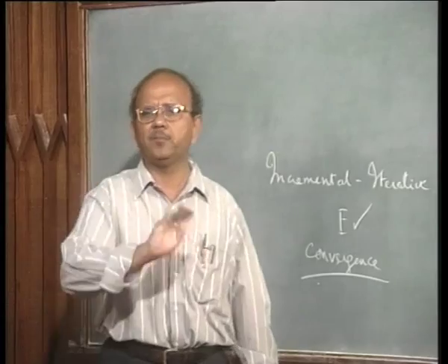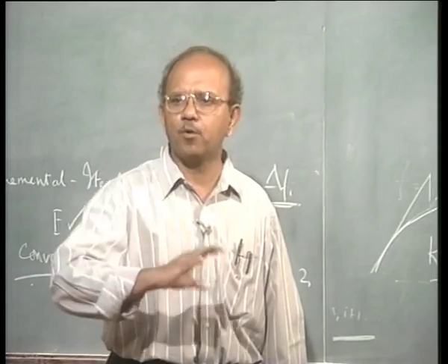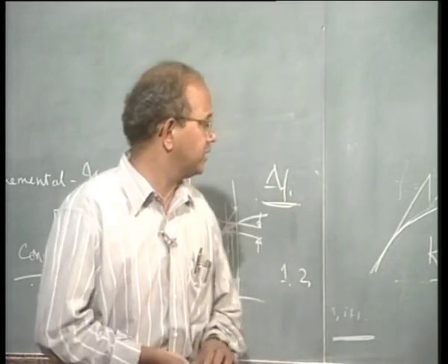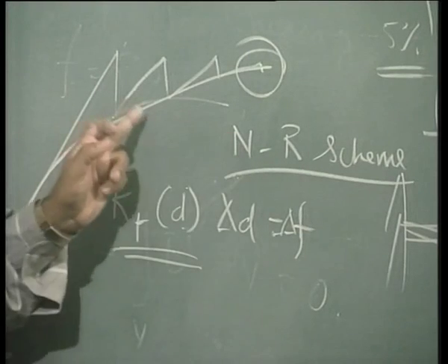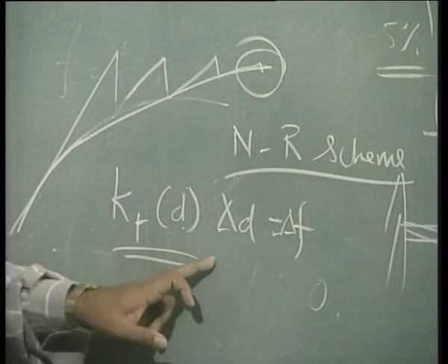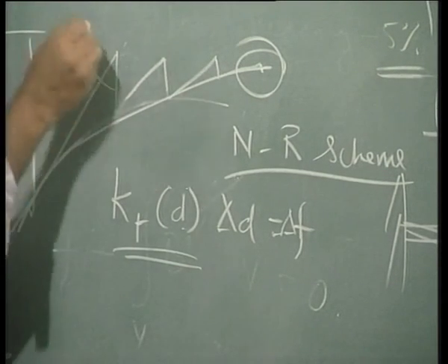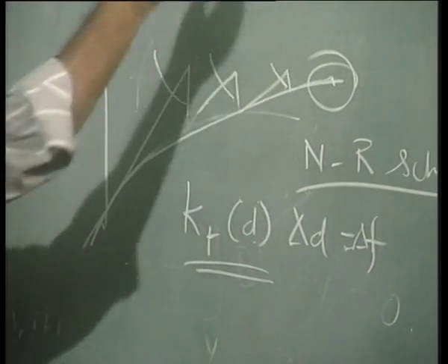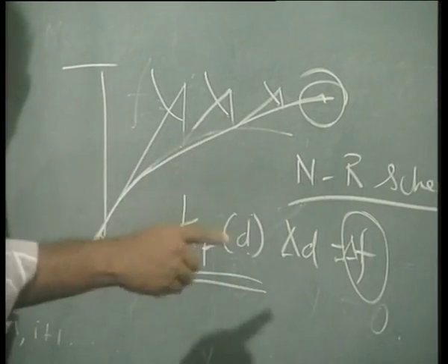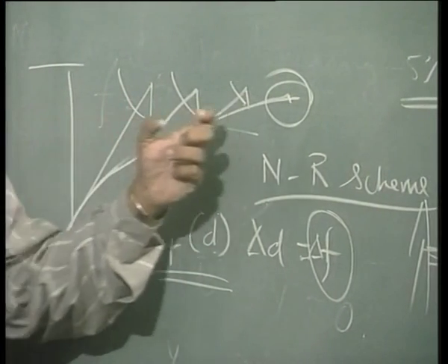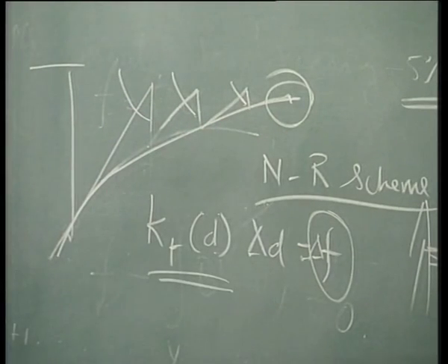I apply it, say for example in 10 steps, just for a small calculation. Let us say that I take about 4 increments to converge. What is an increment? 1, 2, 3, 4. 4 increments to converge. In each of these steps I solve this equation. So, first step, that was the error, second step, that was the error, and finally the error is very, very small. So, on the right hand side I have the errors being shifted from left to right as I move in the increments. Now what does this tell you?